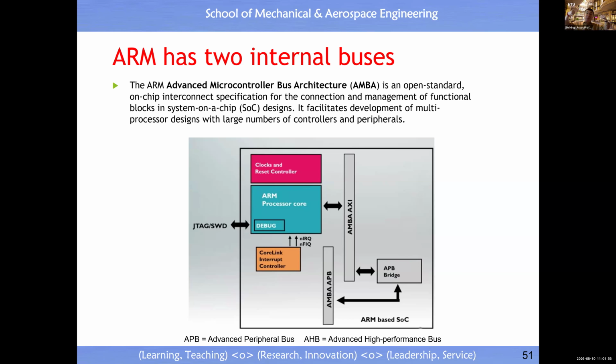That means we double the register, so that means double the capability for the same register. Actually, you have two, like a twin. One address bus is being used by one register, and you can use another address bus for another register. Then you can do a little bit of parallelism, where two addresses can flow out at the same time. You will halve the time.